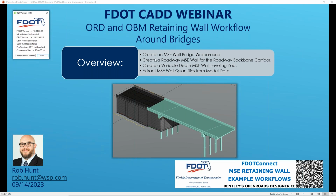What we're going to go through this morning, just a quick overview. We're going to create an MSE wall bridge wraparound. We're going to create a roadway MSE wall for the roadway backbone corridor, create a variable depth MSE wall leveling pad, and extract MSE wall quantities from model data. And the image that I have shown here is just an open bridge modeler model that is attached to the file that we're going to be creating, and kind of the end result of what we're going to be looking at. You can see the roadway backbone, we've got some MSE wall, we've got a leveling pad target, and that wraparound that we talked about.